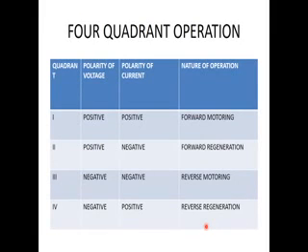The drive can operate in four quadrants, based on the voltage and current values, which are mentioned as forward motoring, forward braking, reverse motoring, and reverse braking. For more information, this four-quadrant operation can be explained using the example of a hoist or lift.